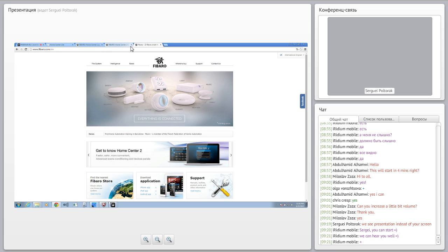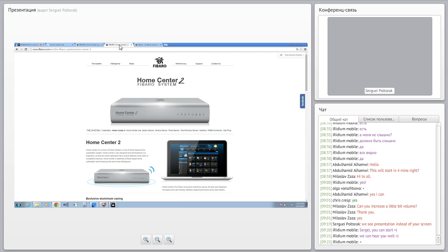That central controller will make all the decisions more complicated than just if something happens, switch on or switch off. For example, time-based decisions, weather or environment-based decisions, and in addition, it will also convert Z-Wave network to Ethernet network and Internet of Things network, including mobile interfaces, web interfaces, and of course iRidium interface.